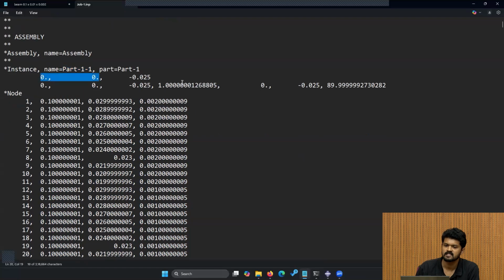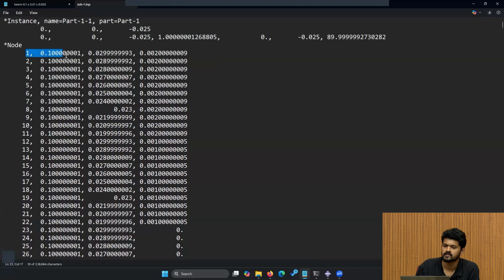This is the geometry information of the part. These are the x, y, z coordinates. First, for extrusion we made a flat rectangle, and then we extruded it in the z direction. So we just need two sets of information: the coordinates of the flat rectangle that we created, and the extruded information. So these are the nodes. Later we discretize the part, and after discretizing, every node will have a coordinate value. These are the x, y, z coordinate values of every node.